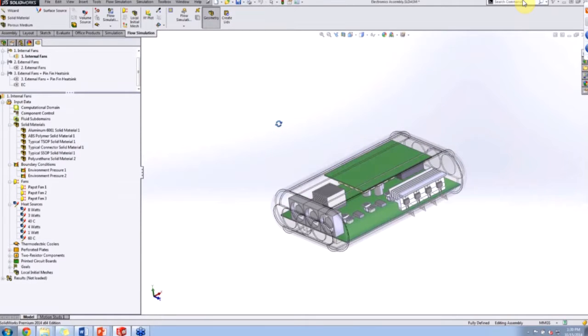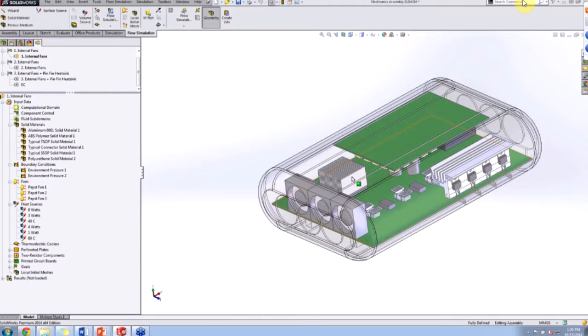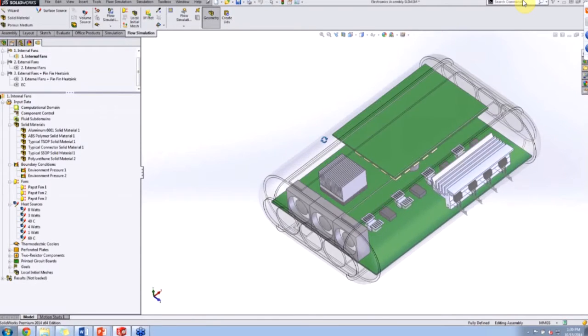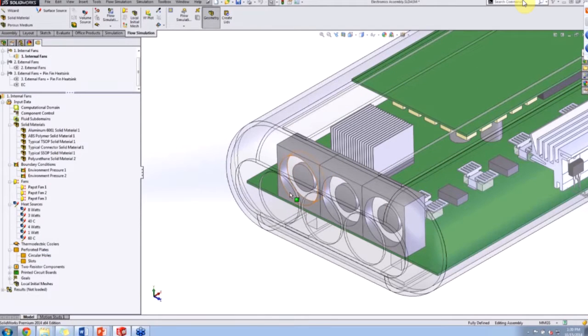All right. So how do we now address the vents and the slits that we had at the top, right? How are we going to actually tell the software that we have air coming out of this body? Well, we can virtually do that within this perforated plate option here, right? And this is stemming from our engineering database again. So if I take a look at those circular holes, again, the body was there, the lids that we created there, that's what's representing the perforation there, the vent.